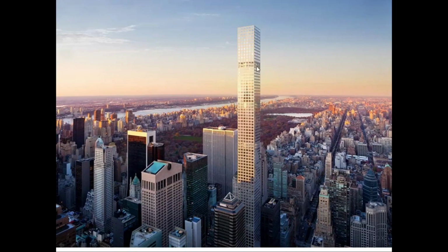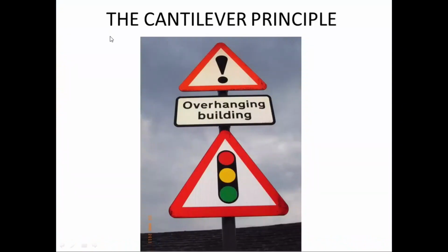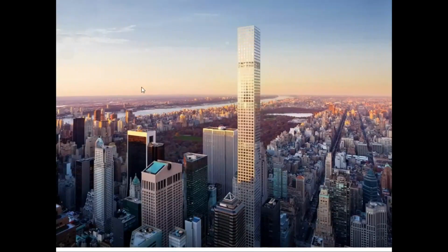But another little clever trick is you can just about see every so often there's an opening. These are, I suppose they probably call them gardens in the sky or something fancy like that. But what they're actually doing is allowing the wind to penetrate, so that at no point is the wind load impacting on more than just that section there, and that section there.